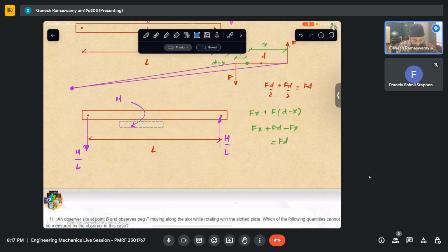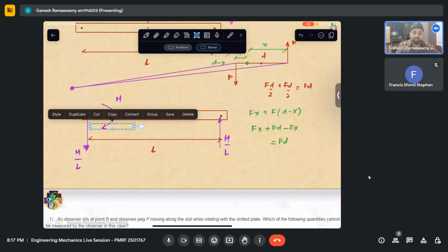Whereas if I were to move this couple here or here or some other point, in all four cases the bending moment diagram will be different. The bending moment diagram will have a jump at the point where the couple is applied because bending moment diagram is an internal effect. Sliding vectors connotation is with respect to external effects.